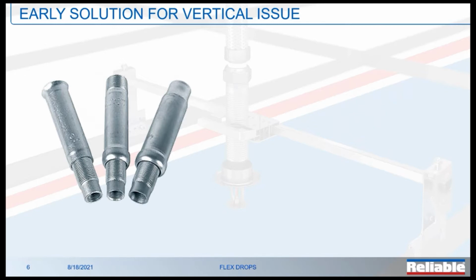These would have somewhere in the neighborhood of an inch, plus or minus, adjustment. That would allow that slight adjustment of the concealed sprinkler for variations in the ceiling height, which are known to occur. You could get within that inch and a half maybe range and spin these up and down. And we were able to accommodate the vertical. So again, still available today. I don't know how much they're being used, but they're out there.